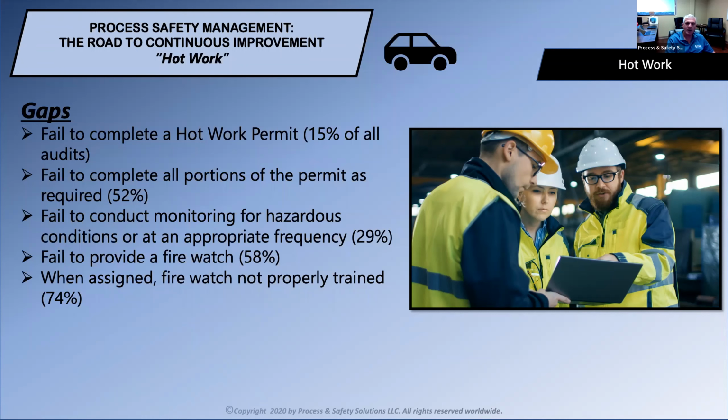So that's a high number of incidents where they have a permit in place, but they failed to complete portions of that permit. If you have a permit and boxes aren't checked, etc., that is a violation of your own policies and procedures. So a part of PSM is making sure that if you have a policy and procedure in place, that you're following that procedure as you have identified.